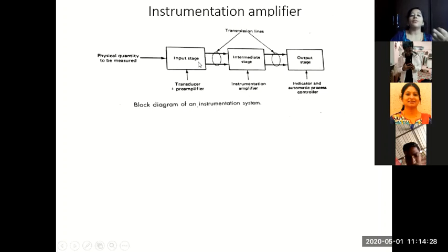And they will be very useful in all your project works. I don't know how many of you would have tried some mini projects. Wherever you need some better amplifiers, we'll use the IC version of the op-amp instrumentation amplifier. That's the best one which can be used for amplification. Okay. It rejects noise, or it reduces noise, and it gives you very high gain also. And controlled gain. You can control the complete gain from minimum to maximum by using a resistor. Is it clear? All that is possible.